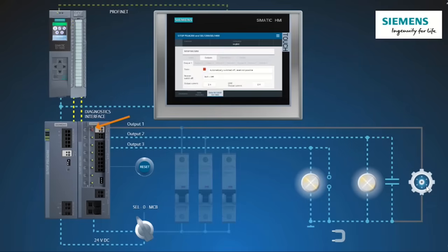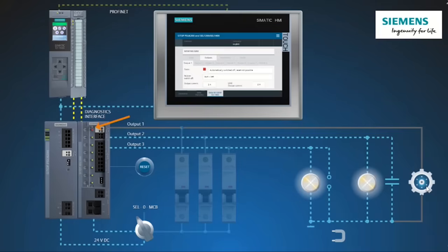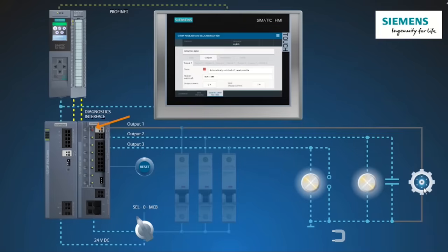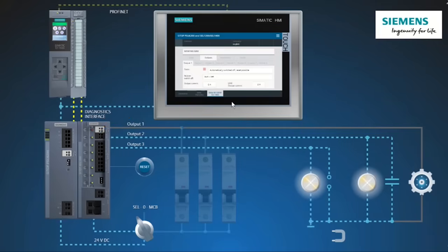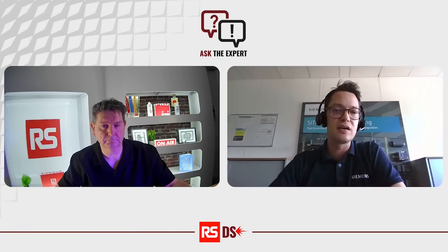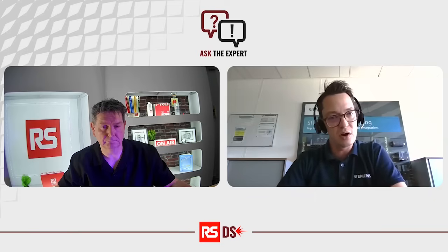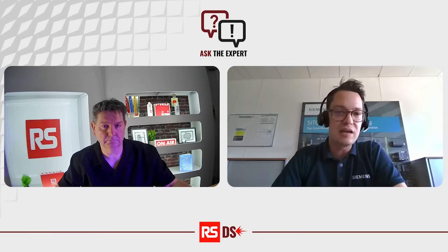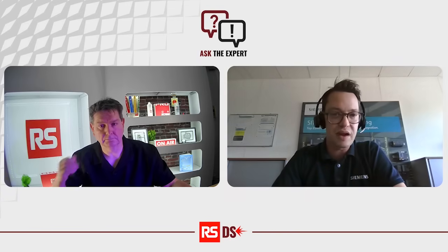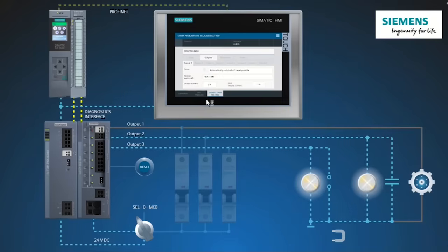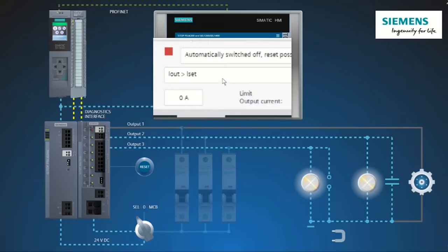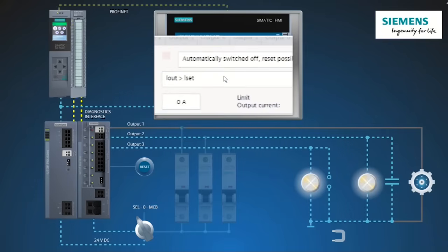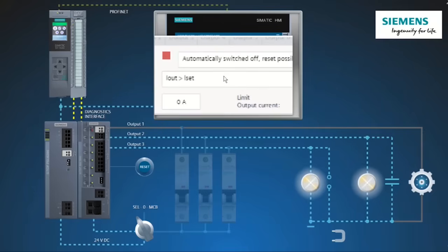and then I will repeat the same process. I will block the motor. The output current increased, and now we have the feature that the selectivity module will grant up to 150% of the output current. It will not limit it. Yeah? And in that case, after 5 seconds, the selectivity module will know something went wrong, something must happen, and will turn off the output.